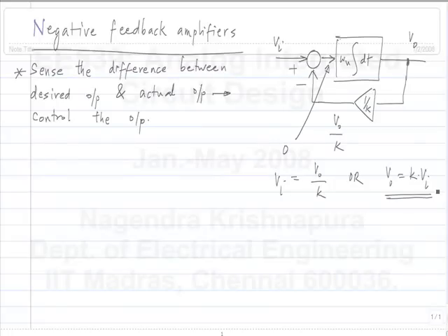So this is how you would make a negative feedback system. To make a negative feedback system, you need an integrator in the forward path, right? So you integrate the difference between the input and maybe some fraction of the output, and drive an integrator using it. So the integrator reaches steady state only when the input is 0. So that means that the error that you sense, that's the negative feedback sensing error, is 0. Okay. So the output will be a desired function of the input.